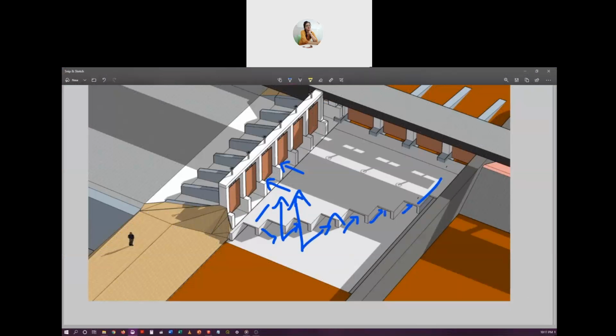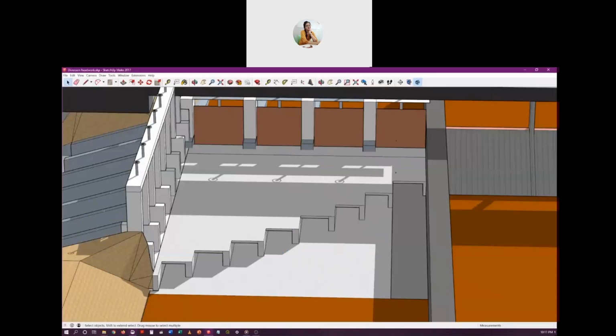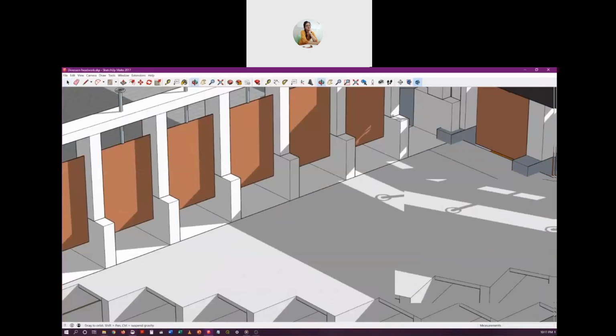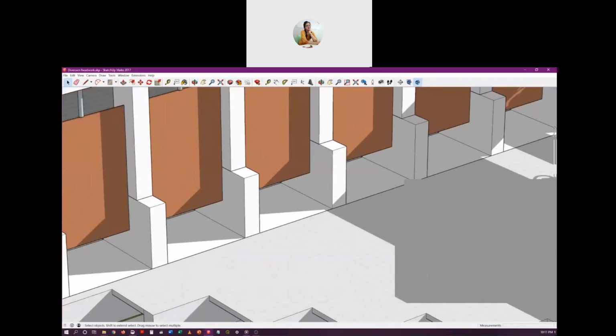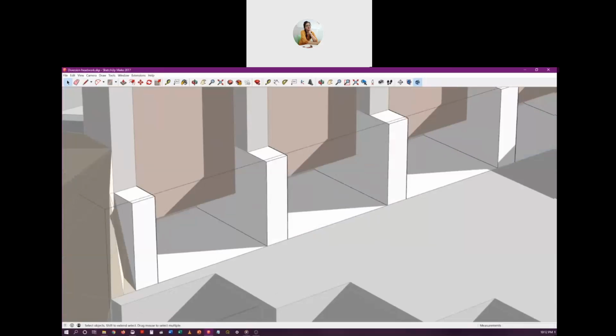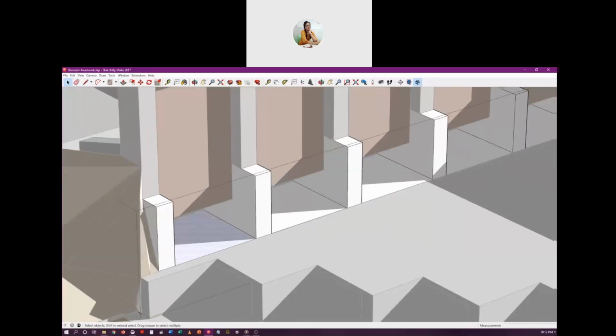Sometimes these tunnels may not be necessary if the natural riverbed is much below the sill level. Sill means this level, that is the threshold of this head regulator, is called the sill. If the river bed itself is much lower, suppose 2 or 3 meters lower than this level, then these kind of silt excluders are not needed, because the lower part is already much lower than the sill level.